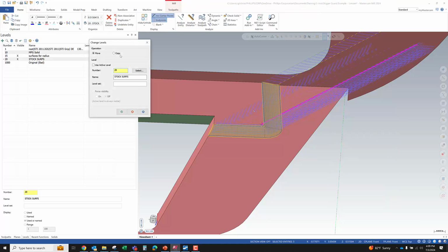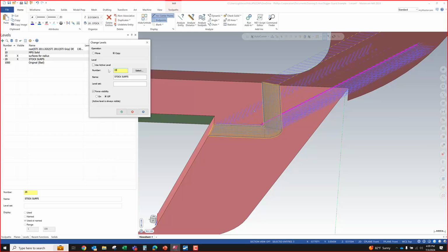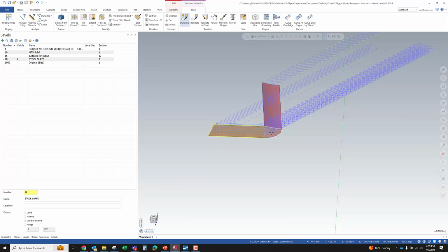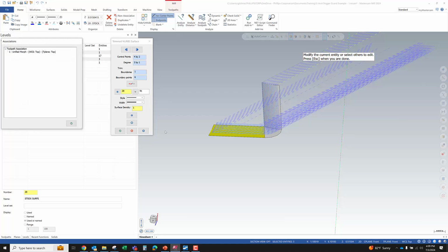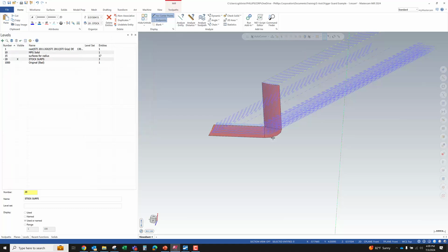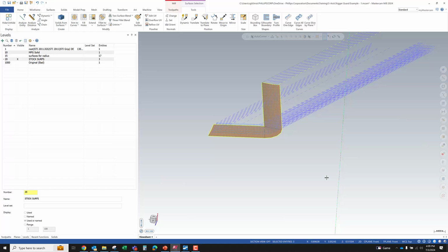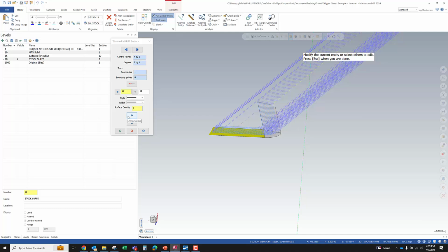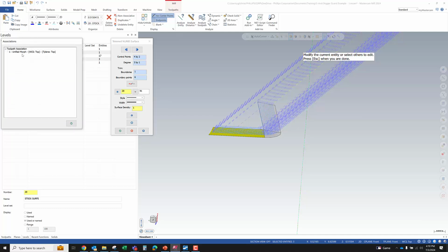Let's go copy 215. Okay. Something that is new, by the way, I've got these 3 surfaces. I'm going to select those surfaces. I should have copied them originally. I moved them. That was my mistake. I want to figure out, hey, can I just manipulate these, or are these my surfaces that are tied to my toolpath? If I do analyze entity, they've got this kind of new option here for association. So you can actually see which toolpath that surface is tied to.